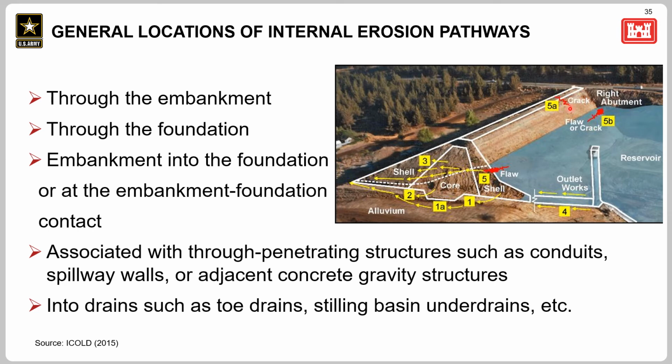or flaws in construction. So thinking about those locations of where internal erosion pathways could exist helps us think about the design process, the construction process, whether there are design flaws, construction flaws, material types that are incompatible and in contact with each other, whether there are geologic anomalies that concentrate seepage, or reasons why cracks might form. So that's what we're looking for when we're characterizing a site.